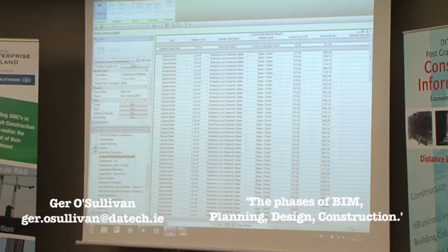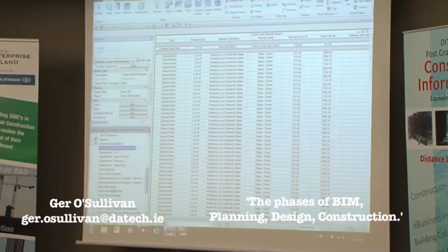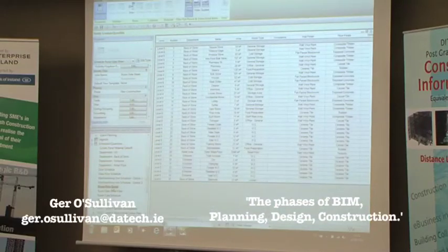So we then can look at, say, the information for the rooms. So the room data sheet, reading those rooms, getting back of store, the name, the area, the room type, the finishes. So the room I added is there, stairwell, 21 square meters, don't have a room type associated with it. So we'll pick up, say, general storage for the moment. And then it'll put in my finishes.